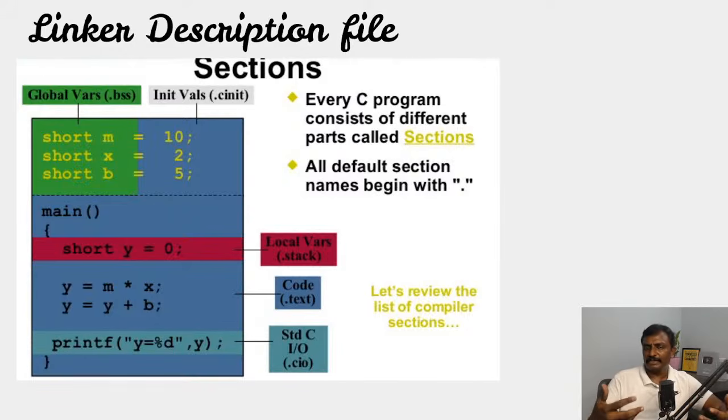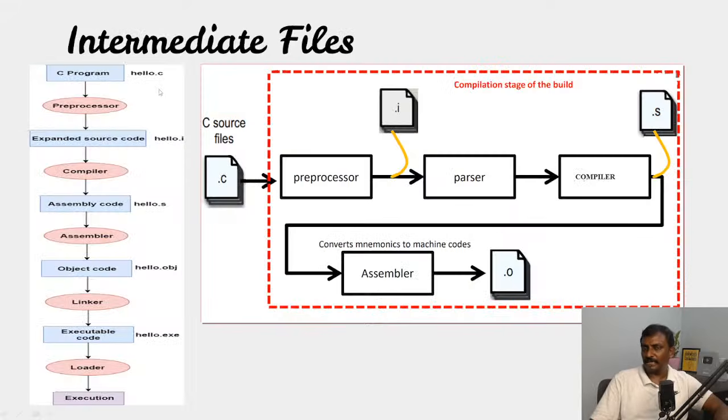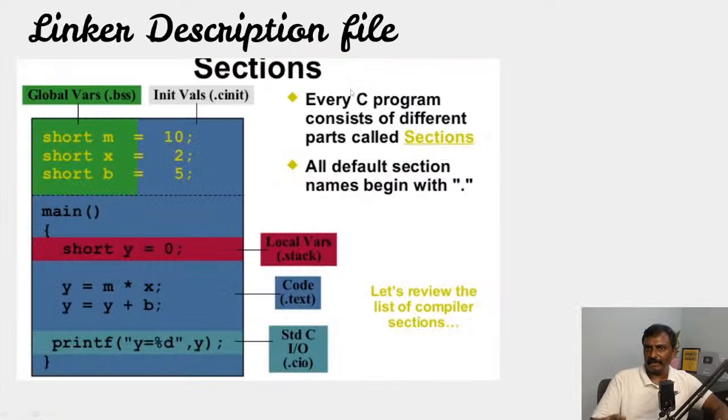The linker file will have different extensions, like a C file comes with .c extension, whereas the linker file depends upon the manufacturer. If you take Xilinx or Analog Devices, they come up with .ldf. For Code Composer Studio, for Texas Instruments, they come up with .cmd. So they come up with their own extensions, and the language will be quite different, but the concept is the same.